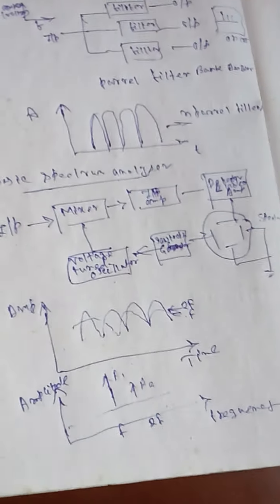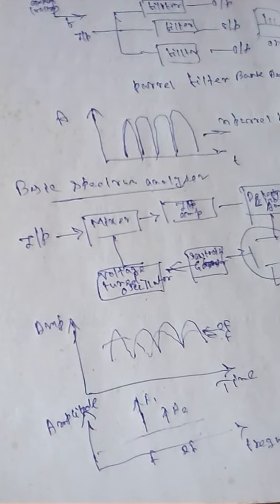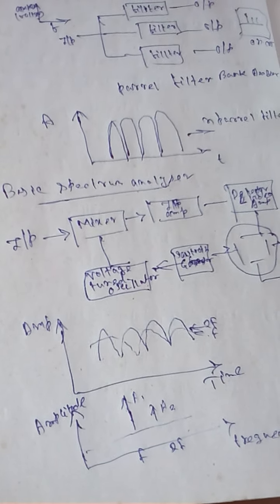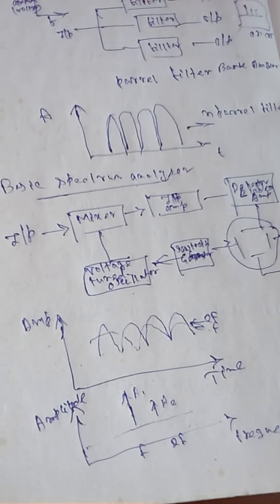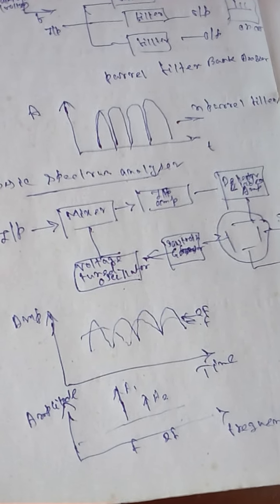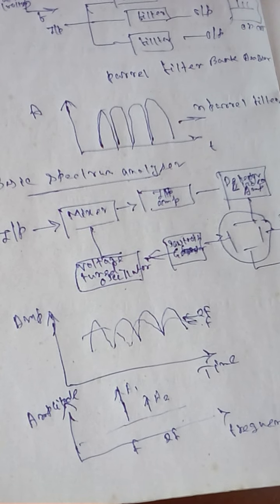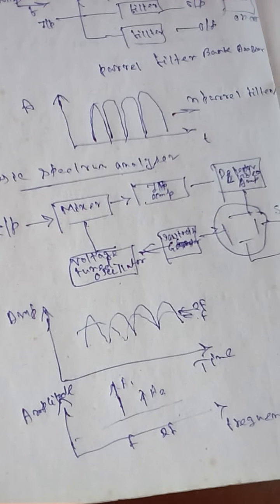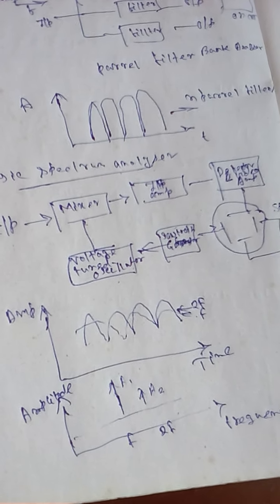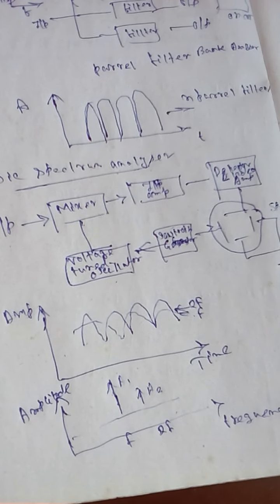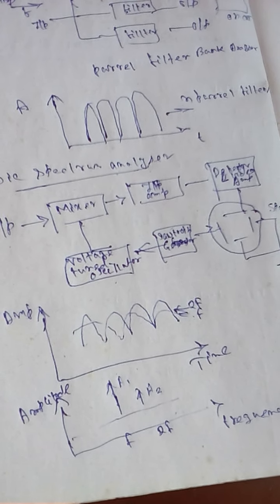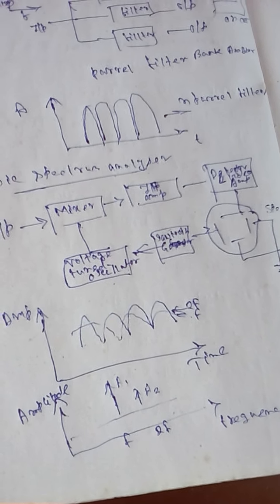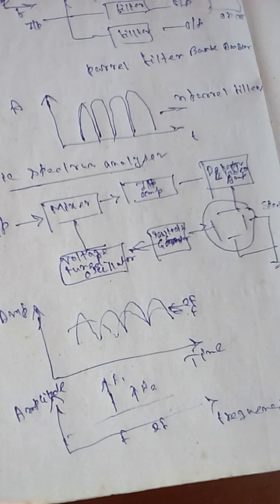So what happens in the circuit? The input is first mixed with the oscillator, and the sawtooth generator provides the sweep waveform. The oscillator sweeps from a minimum frequency, F min, to a maximum frequency, F max. It beats with the frequency components of the input signal and produces the IF when a frequency component is met during its sweep.